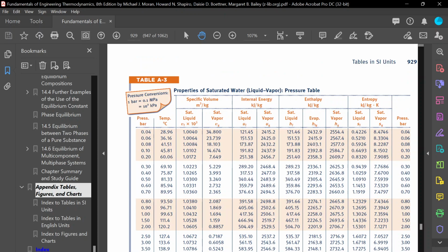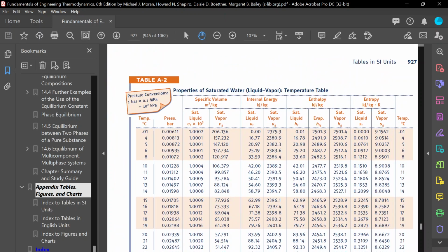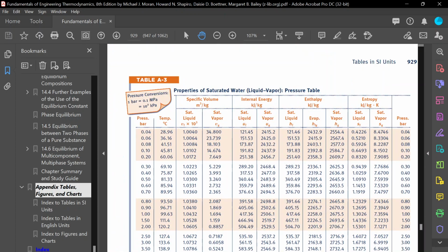One thing we can do is to look at this temperature table. This is not something I like to do, and a lot of books don't really agree with this. But Moran, the book we use as a textbook here, does this. It's pretty close to the real answer. I usually would rather assume that C is constant and go that route, or read the C from a table.